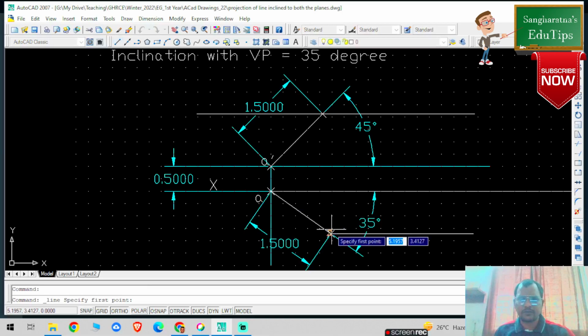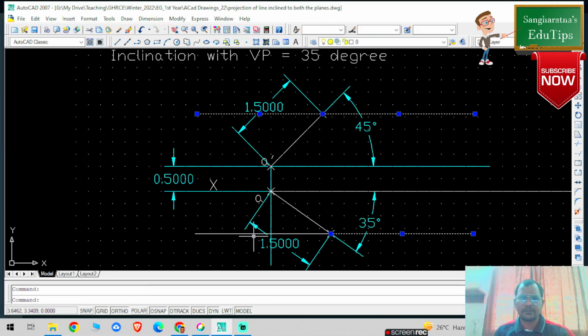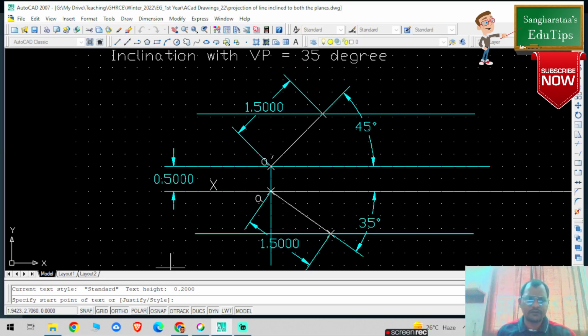Similarly from this particular point, I am drawing one locus, press escape. From this particular point, I am drawing another locus, press escape, and then immediately convert this particular locus into cyan color, okay, press escape. So write down the text and naming the text. So these commands you need to always use randomly. So whenever you want you can write it down, rotation angle, okay. So this is my point basically B1 dash, and this is my B1, okay.